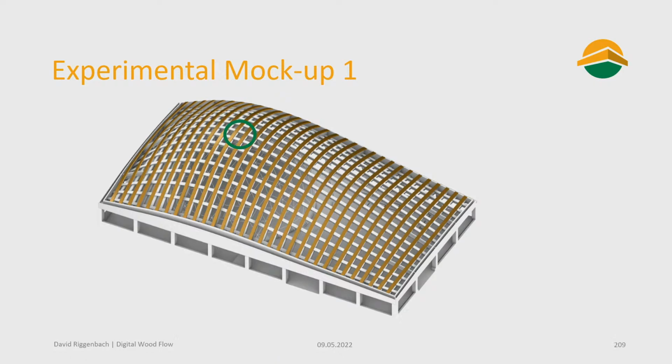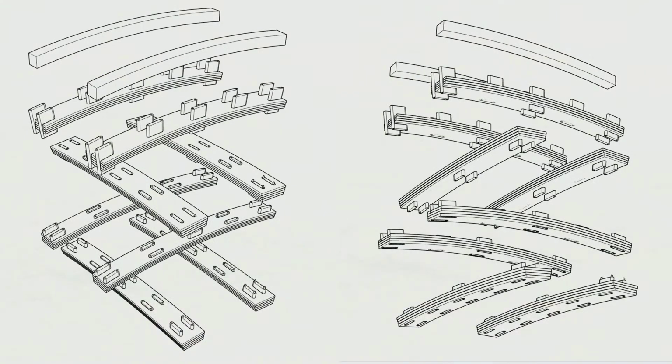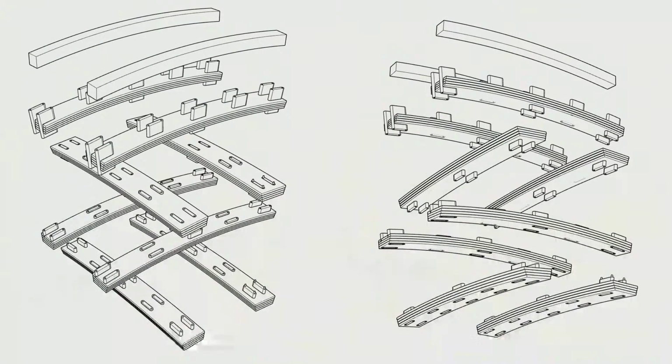And we did a first experimental mock-up. So that's located at the top of the structure. Here you see an explosion drawing, and this was more or less fully designed by Hermann Blumer. So the idea was, here you see 4 layers of grid beam, and every beam consists of 4 lamellas, 39 millimeter thick LVL. For the connections, we used a quite traditional way to combine different wooden sections by using shear dowels, which are also made out of wood material. So you see here, there is always a cross connection and also a shear connection in between through crossing points, and it's all made in the same system.